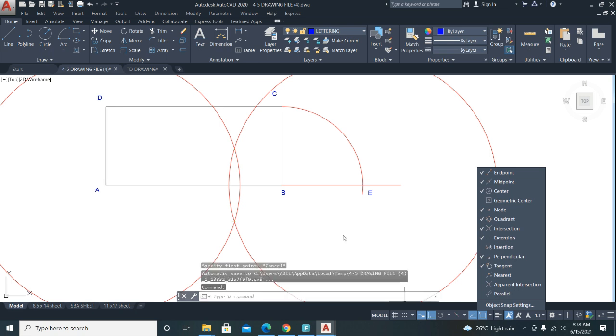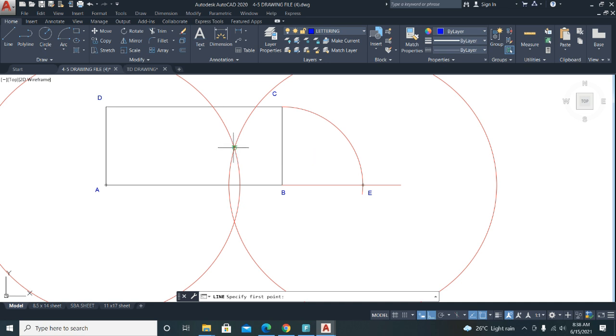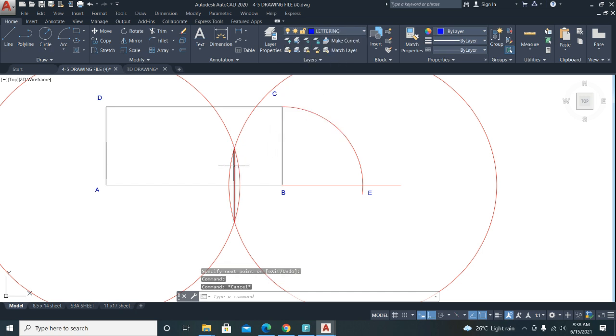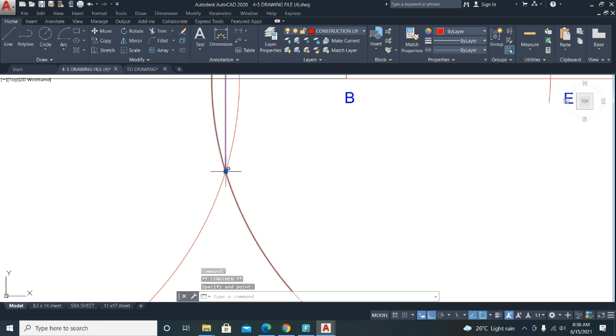You click it. So you come in at this point and you're drawing a line from here to here. Press enter. This line should be in your construction layer. Now extend it a bit. In order to extend the line here, you can zoom in by rolling the wheel mouse forward, lengthen. This I have shown many times for you all how to do it. Going down to the below one, same thing again, wait for it to highlight, turn red, and then come downward, click on it.